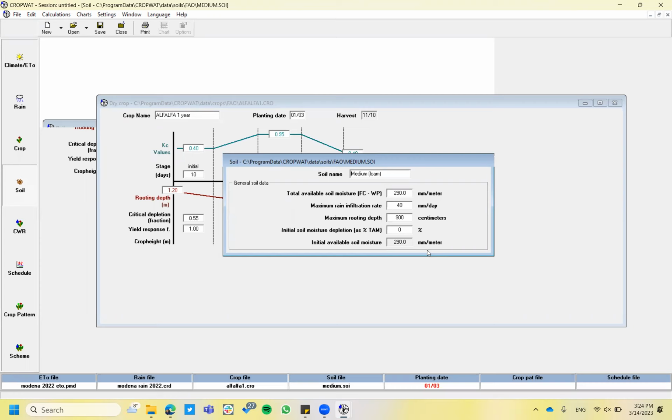If the soil isn't able to infiltrate the water at that rate, then less water will infiltrate and the rest will be runoff. So what we want is our sprinkler to be the same or less than the infiltration rate of the soil. We want the soil to be like a sponge for my sprinkler.